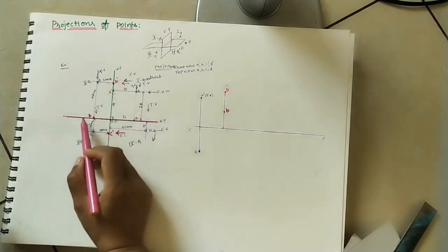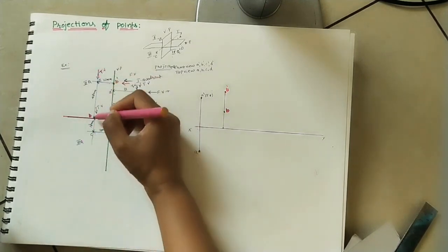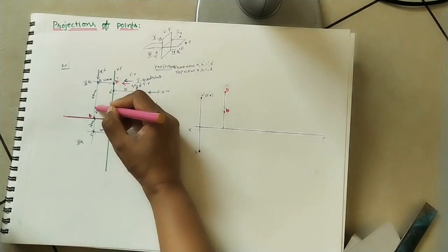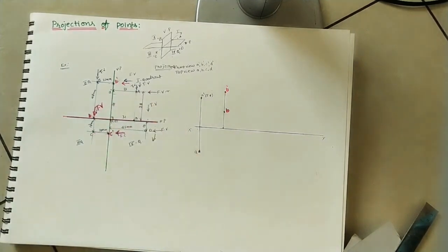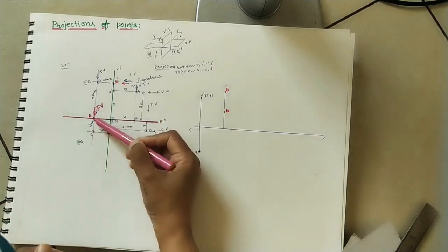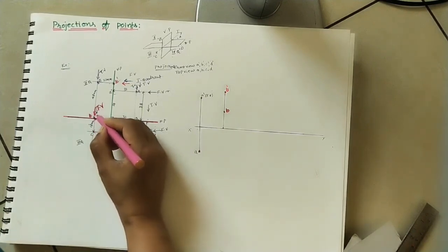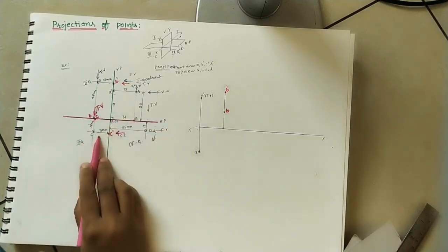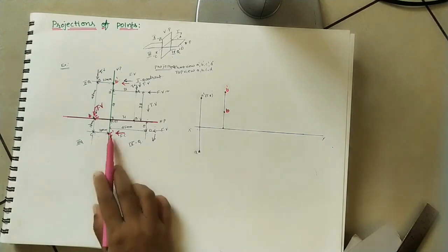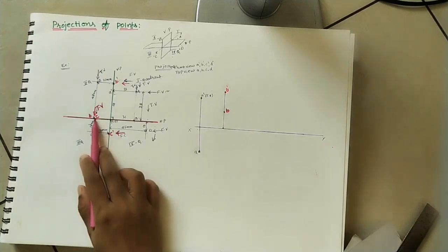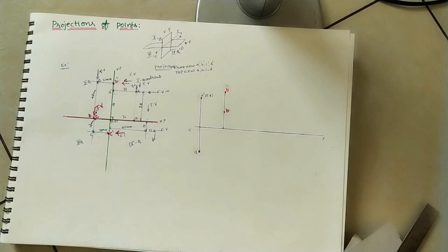Okay. And then what is the top view of this C point? So this is transparent. So this is the top view here, or we can take the top view here for the C point. If we see from the top of the C point, so C will come here. Okay, how much gap is it? 20 mm gap. So mark C point here, which is 20 mm distance. Okay, C dash is coming here, C is coming here. So this is a 3D view.